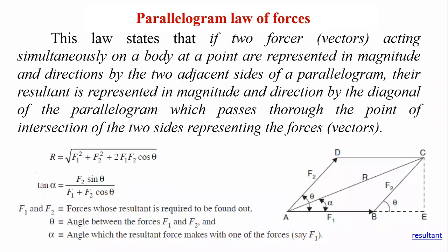In this condition only, this parallelogram will be applicable. If there are more than two forces, this parallelogram will not be applicable. And the forces should also be concurrent, meaning they should pass through a single point. A coplanar concurrent force system should be there. Then and only then will this formula be applicable.